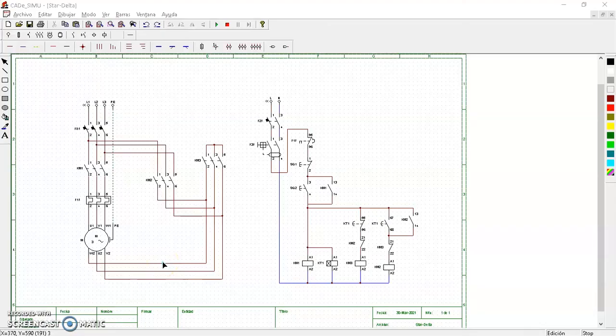The last example of this post consists of a star delta start. For asynchronous motors with a power output of less than 1 kW, a direct start is used. If this power is excessive, other methods are used to reduce the voltage during the transient, by reducing the starting current: electronic starter and star delta starting for delta connected motors.